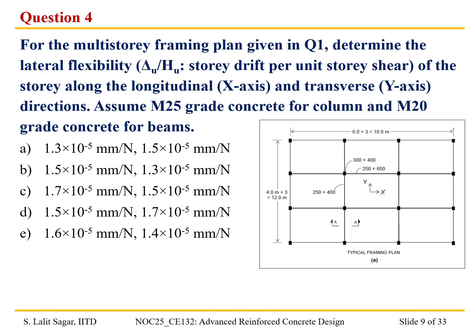And in question 4, the question is that for the multi-story framing plan given in question 1, determine the lateral flexibility, that is delta u by hu, which is also known as the story drift per unit story shear.